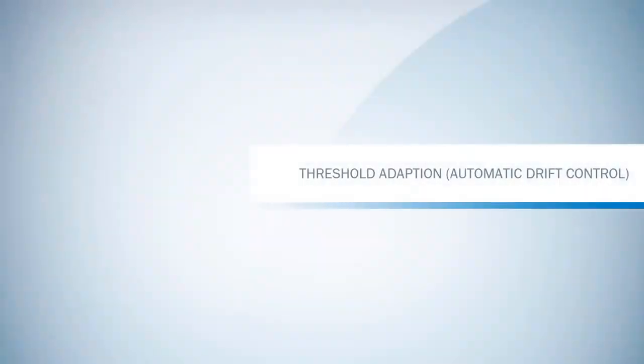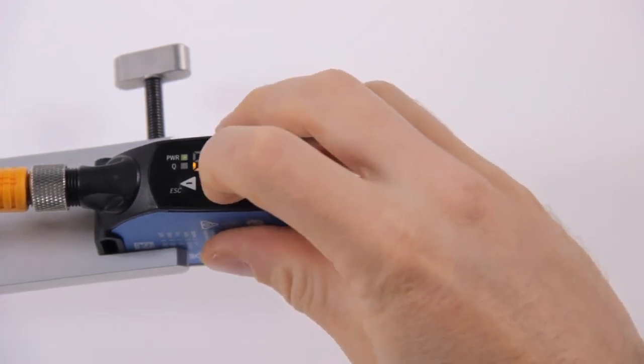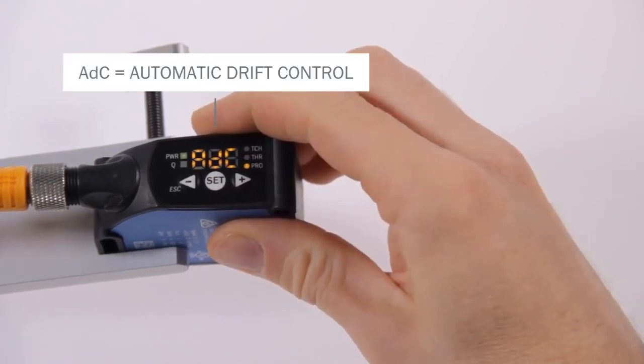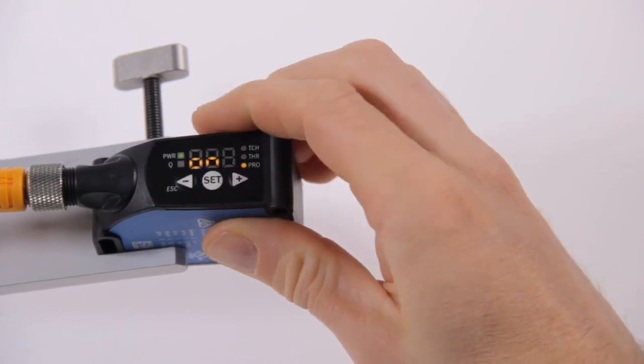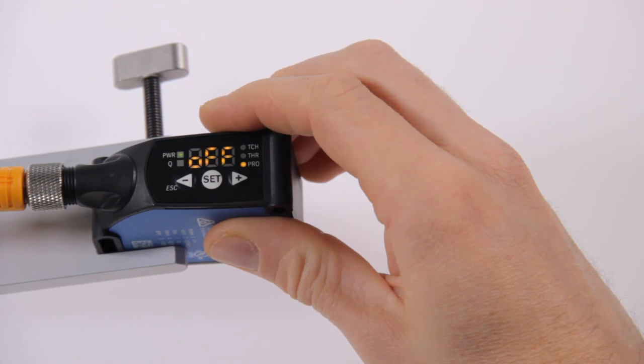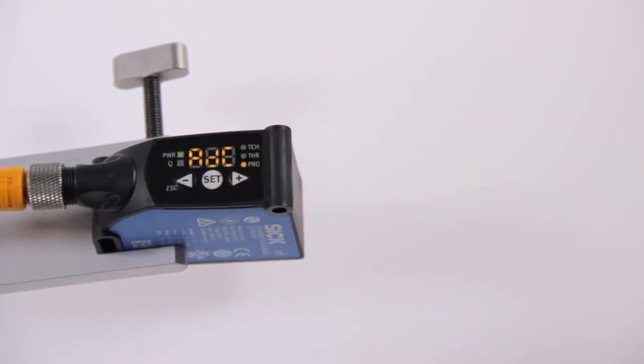Threshold adaptation, automatic drift control. In some applications, a lot of dust and dirt is in place, and it might be necessary to adjust the switching threshold from time to time. This can be done by using the automatic drift control function. Use the plus and minus buttons to move to the menu item ADC for automatic drift control. Confirm the menu item with set. The feature can be switched on or off by using the plus and minus buttons and confirming with set. As default factory setting, this feature is on.